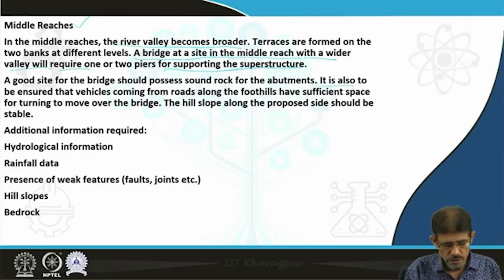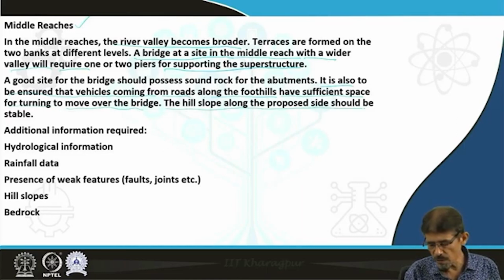It is also to be ensured that vehicles coming from the road along the foothills have sufficient space for turning to move over the bridge, and the hill slopes along the proposed site should be stable if we are going to construct a long bridge.